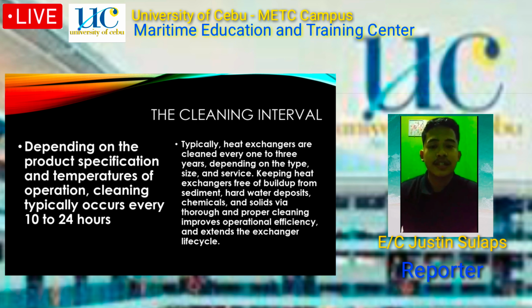So next is the cleaning interval. Depending on the product specification and temperatures of operation, cleaning typically occurs every 10 to 24 hours. So basically the interval of cleaning is around 10 to 24 hours. And next, heat exchangers are cleaned every 1 to 3 years, depending on the type, size, and service.